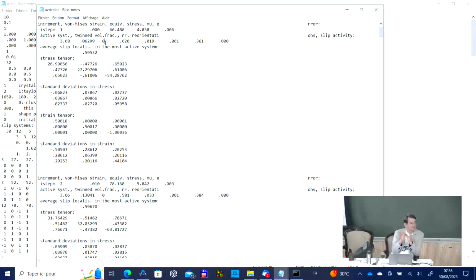And then only one variant. So the number of grains is not changing in the simulation, but certain grains, at a given moment, switch into twin. You must have a very large number of orientations, because in a statistical manner, if we examine twinning, this is quite correct for texture evolution, and even for strain hardening. The simulation is working quite well with respect to the experiments.